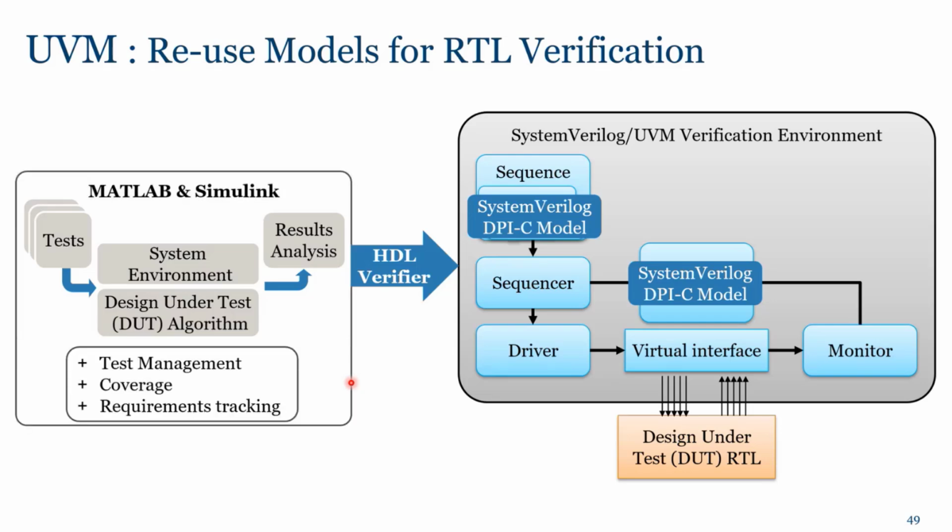In that case, you will have all the test management, the coverage, and the requirement tracking in MATLAB and Simulink. HDL Verifier eases the transition between the MATLAB and Simulink environment and a UVM verification environment. It goes without saying that what we are generating here with the UVM verification environment is a standalone environment. So you can go and run it, for example, in QuestaSim without the need to call MATLAB and Simulink tools during the simulation.